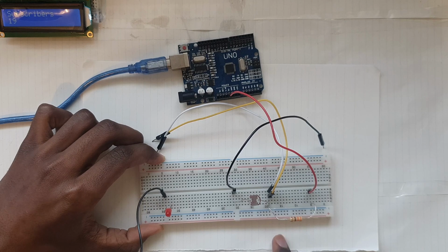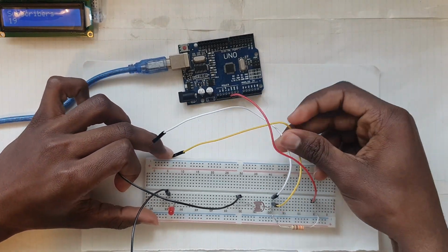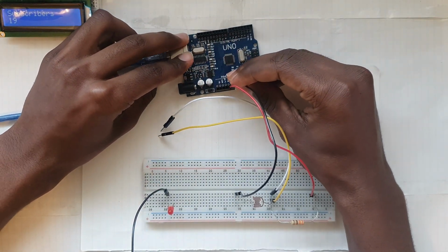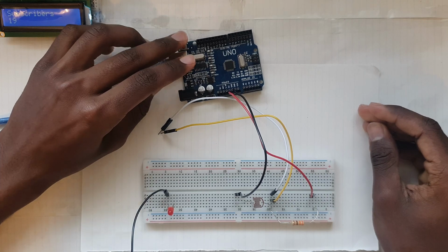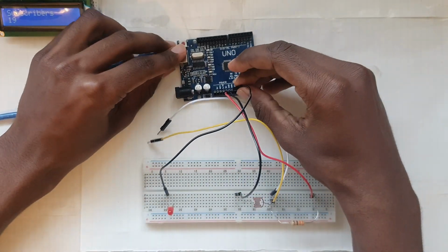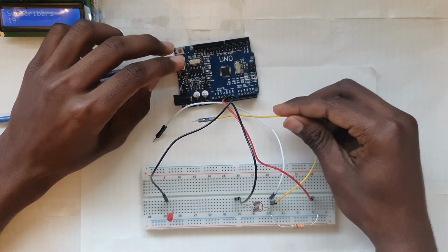In the same column, you also want to plug in 2 wires. I've chosen yellow and white. At the end of the LDR, or at the end of the resistor that you've chosen, you want to get a black wire or any wire and ground it. A little bit to the left, I've plugged in my LED. You just want to make sure that it's plugged correctly. The short end is going to be the one that's grounded, so I've used a black wire for that one.